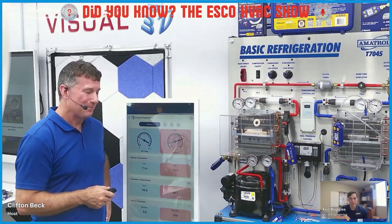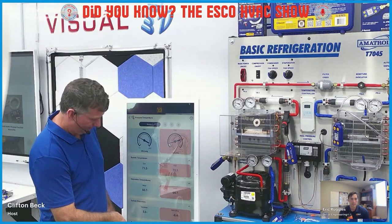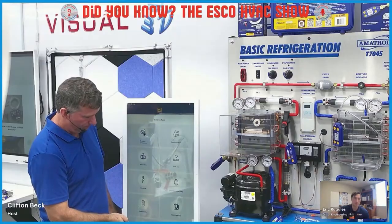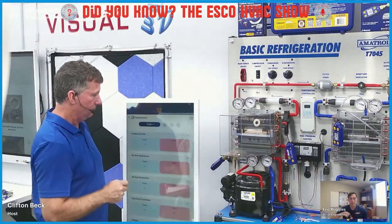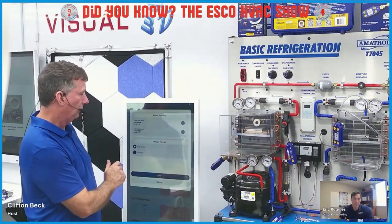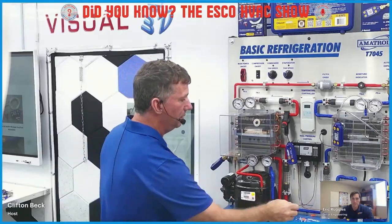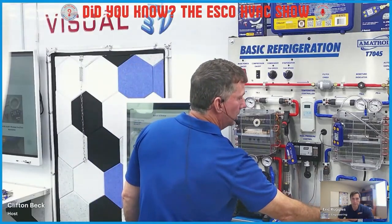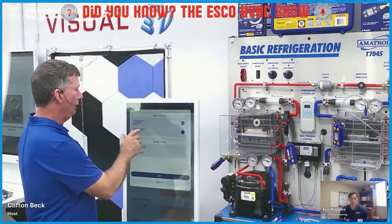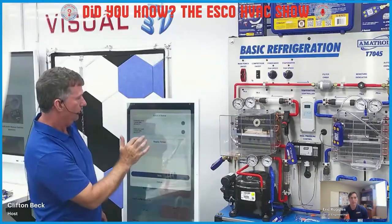All right. So let's go back, hit the button to go back to the sessions, the main session button, the second one in. Yep. That works too. Then go up to upper right, the psychrometrics. Connect those two DO sensors, the psychrometers. Okay, and on this one, we'll be using the long ones. Yep. 9452, we'll be using that one. So this is broken between supply and return.